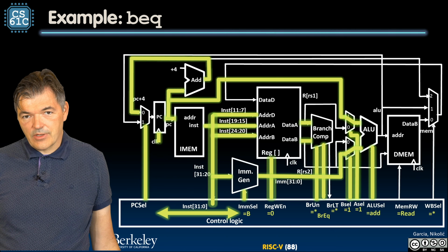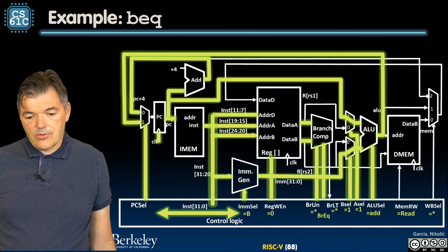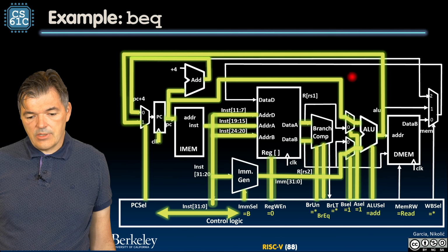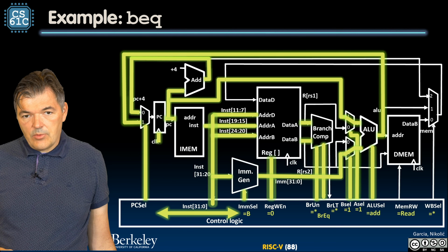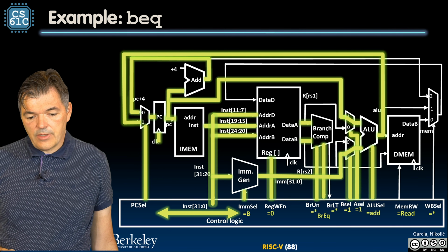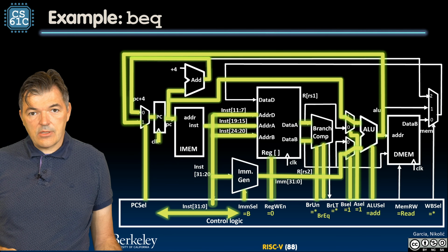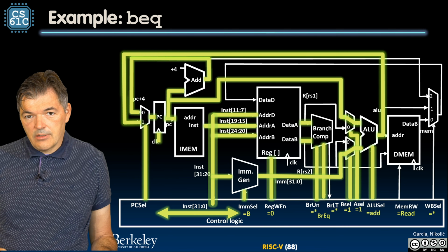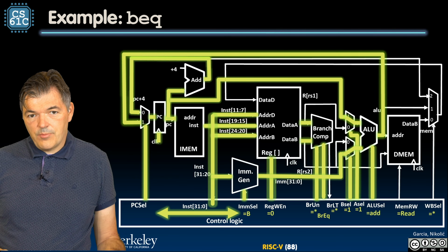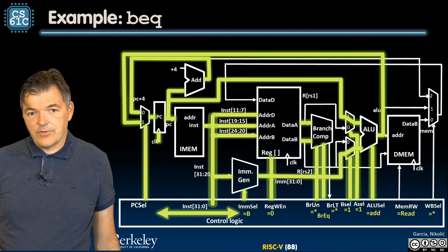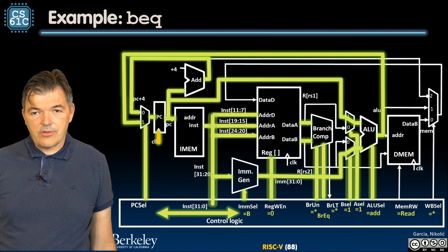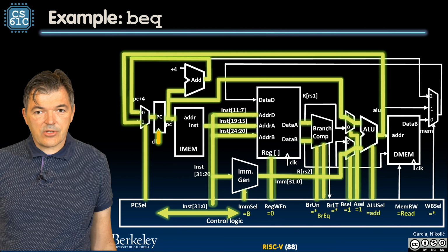So we'll figure that out after the ALU completes its operation, its addition, and presents this new value at the input of the multiplexer. At that point, we have both of those signals valid. One of them that is set by the PC select propagates into a program counter, and that completes the instruction. Although the clock ticks everywhere, the only state that gets updated is the value of the program counter. So that is what wraps up the branch if equal instruction.